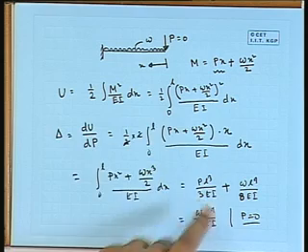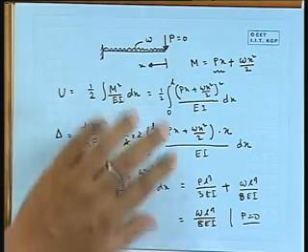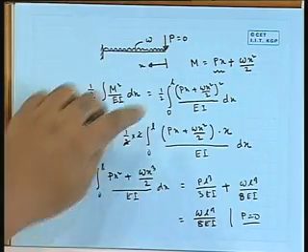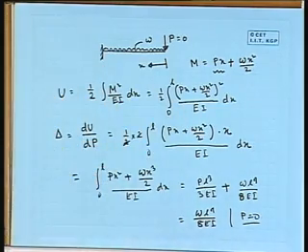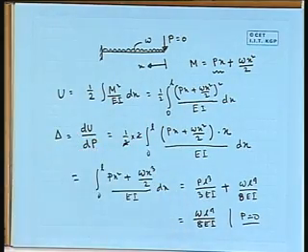So, this P L cube by 3I part is also there. Say the beam is subjected to this load plus this load, omega plus P. So, this part is due to the point load, and this part is due to the uniformly distributed load. Now, if that part is not there, it will be dropped out. If that part is there, then this is the value. So, I could have put it 0 earlier, okay. So, we need not carry one of the components. Unnecessarily I have kept it, just to get the feeling that this part is also there and it will come out, okay.